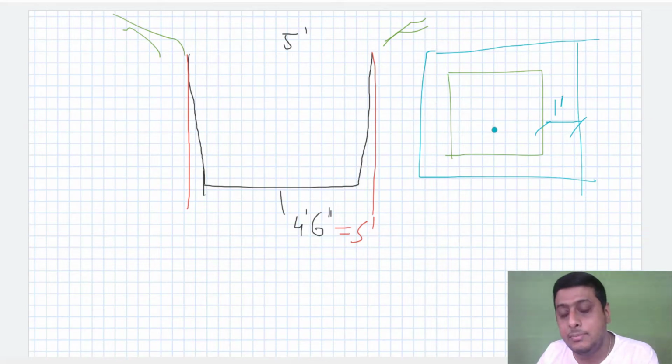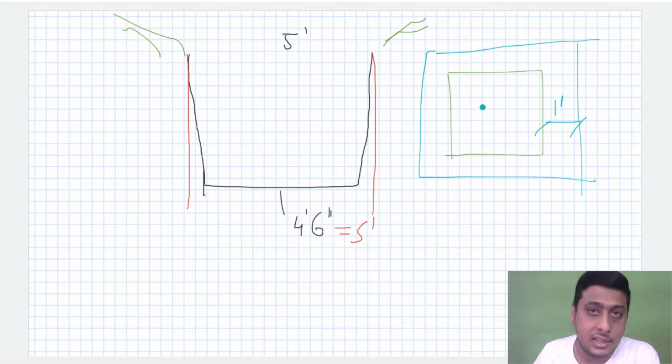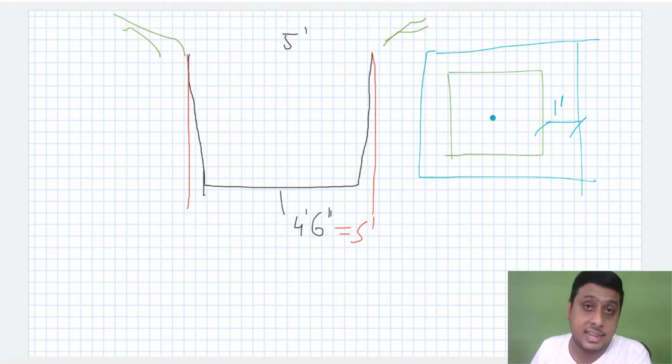This is the reason: if this loose earth is present, when we put the PCC here there will be a lot of movement, so there may be a chance of this earth material falling into the pit again. It may cause a lot of disturbance while putting the concrete onto the foundation, and we have to clean it up again. All these things we should observe and monitor as a site engineer.